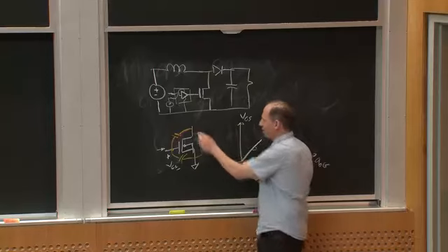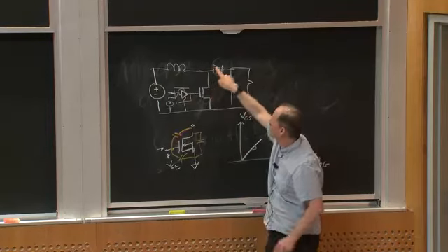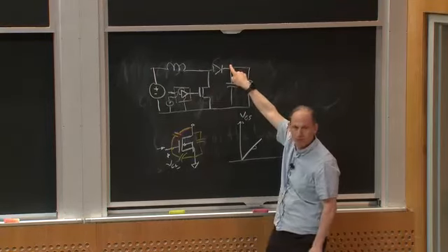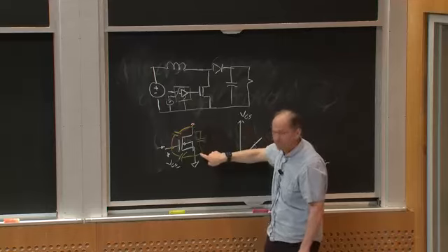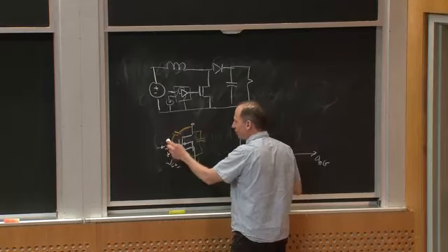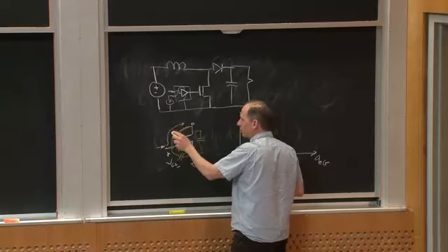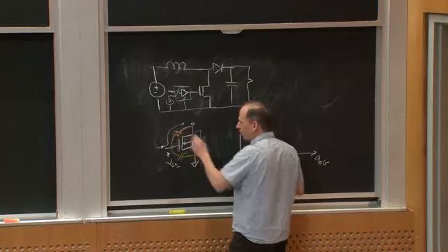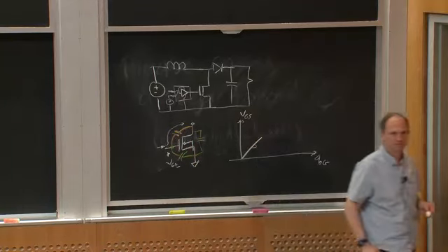This voltage, the output voltage, which was up at some high voltage, maybe 200 volts, starts to swing down. And when it starts to swing down, I need to feed charge in from the gate to discharge this capacitor.